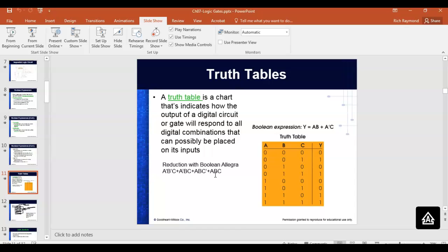So what we do is, there's a zero button, but a truck driver's not going to get out of their truck, go up on the scale, and zero it before they drive up on the scale. So I was tasked with designing a circuit that would do an auto zero. Like every minute, if there wasn't motion on the scale, so it had a motion sensor. If a truck started onto the scale, you don't want to auto zero when something's going on the scale. And then I looked at all the outputs to see if it had any weight on there.